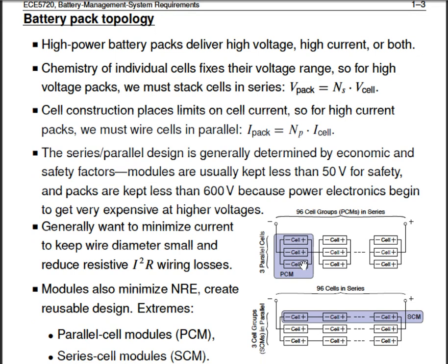Whenever the batteries are connected in parallel, their net voltage is the voltage of the highest battery. Whenever the batteries are connected in series, depending on plus and minus, who is connected to what, the total voltage is the algebraic sum of the battery voltages. Algebraic sum means depending on the polarity you have to add or subtract the battery voltages. So that is what it is. Whenever the cells are in parallel, whoever has the highest cell voltage will be the output voltage of the cell.